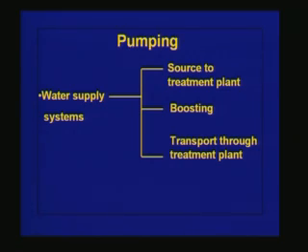We also need pumping because we have to get over the frictional losses that could be coming in the pipeline. Then we also require pumping many times in water distribution networks because the pressures could be very low and we have to meet that minimum 7 meters of head of residual pressure, and we need to boost up these pressures.